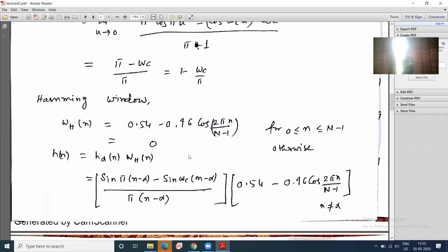If I talk of a high pass filter, it means your passband is high pass. If I talk about a low pass filter, it means low pass is the passband. Other than this low pass, that is your stop band. Therefore, the passband to stop band transition or stop band to passband transition, the faster you can achieve it, the better the design.